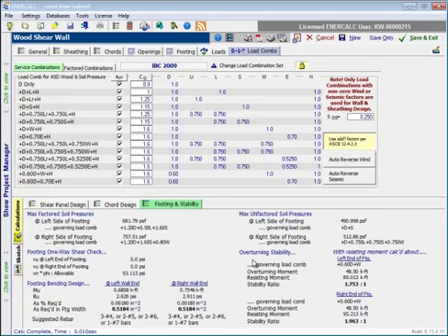And then we have the overturning stability calculations, where we report the moment about the left end of the footing and indicate the overturning moment, the resisting moment, and the ratio resulting, all from this governing load combination, and then the same information at the right end of the footing. So here we can take a look at quickly in bold the stability ratios against overturning about both ends of the footing.